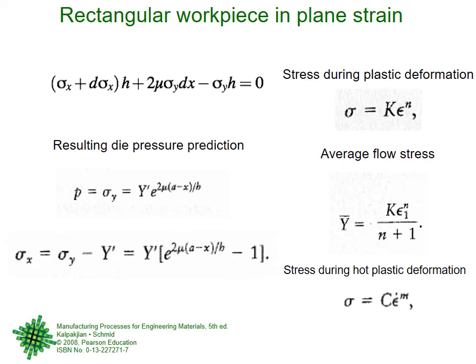You force it into that shape, you remove that shape, plastic deformation will be there, but some of the elastic deformation will be lost. But if you keep the pressure there for some time, not immediately, as soon as you fill the whole die, you don't remove the pressure, you keep the pressure for some more time, then the spring back will not happen anymore and the material will have taken the shape of the die completely, right? So you are starting from some stress and you are finishing at some stress.